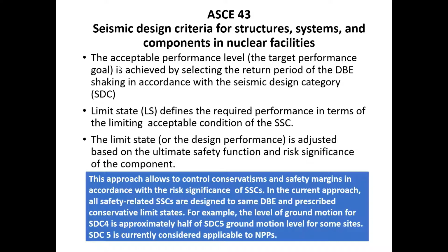but for a given seismic design category, you select based on the performance target requirement. You select the design basis earthquake return period consistent with that category. And so you are already introducing the concept of how to design basis earthquake and how it matches with the performance target. The second parameter, which is very, very important, is